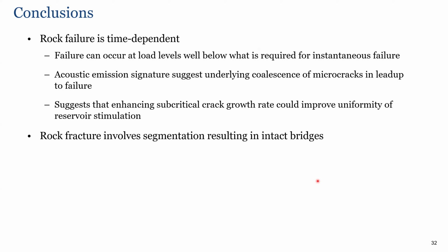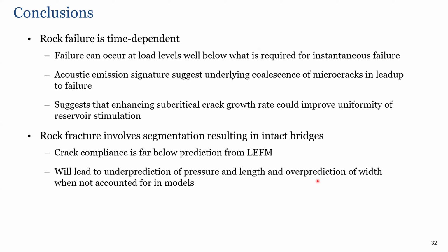And then you can maybe break it with your hands or maybe not. But that thing that makes it still kind of hold together, those are those intact bridges. And sometimes we might need to account for how those impact the compliance of the crack. Otherwise, our LEFM-based model really doesn't stand a chance of matching to data. It'll lead to under-prediction of pressure and length and over-prediction of width, if not accounted for.